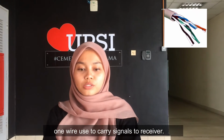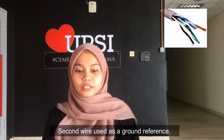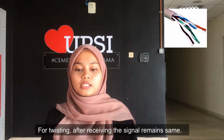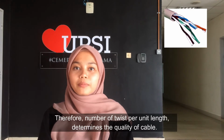One wire is used to carry signals to the receiver. The second wire is used as a ground reference. With twisting, after receiving, the signal remains the same. Therefore, the number of twists per unit length determines the quality of the cable.